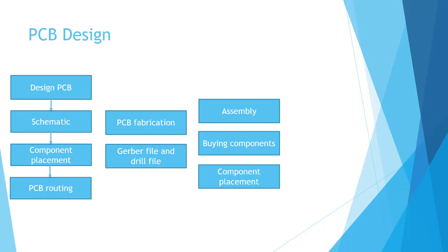But if the schematic library is not created in the correct manner, the engineer should edit the BOM, or bill of material, to send to the assembly. So your component provider will contact you many times to correct possible errors or faults. After that, the components should be placed on the board, and depending on the assembly, you should consider some situations in the footprint and in the PCB library.